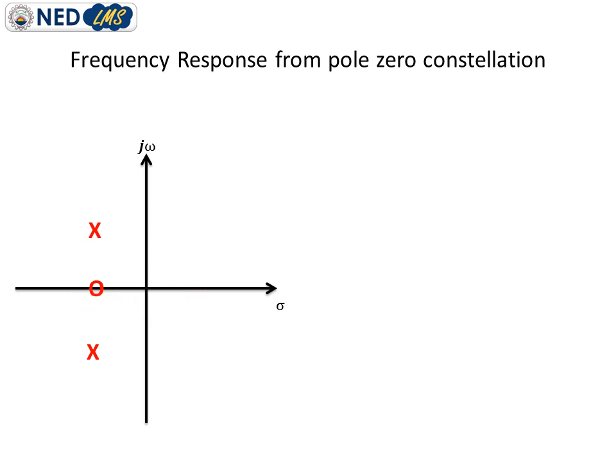It will not affect the stability of the system. But if any of the poles lie on the positive x-axis or the right hand side of this plane, then it will create a problem and it will make this system unstable. But as far as this configuration is concerned, we may comment that this system is stable as both the poles lie on the left hand side of the S-plane.